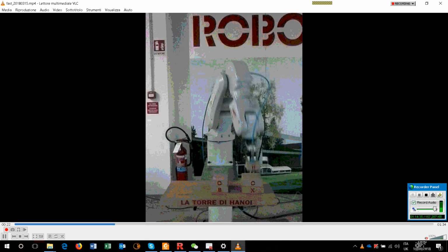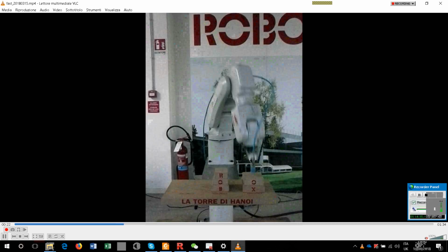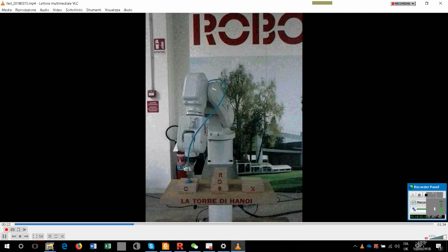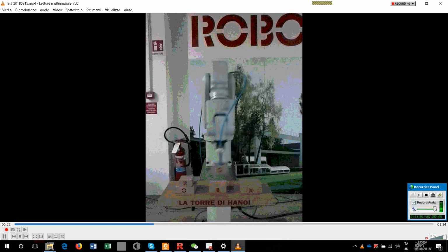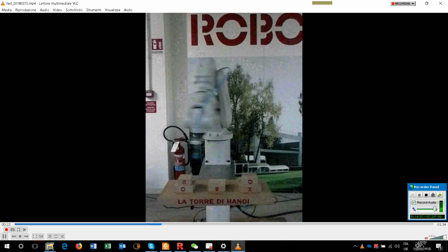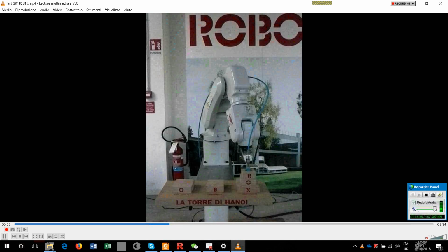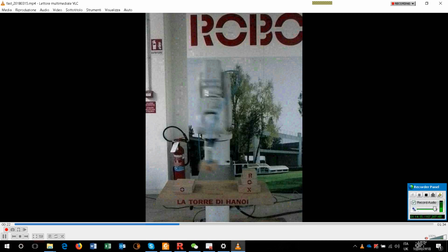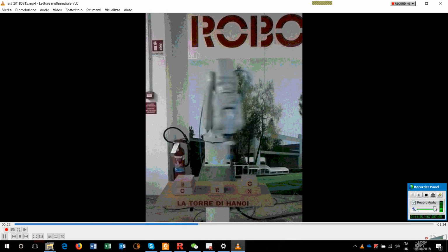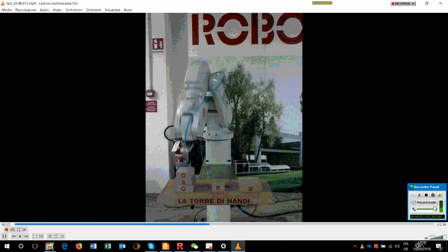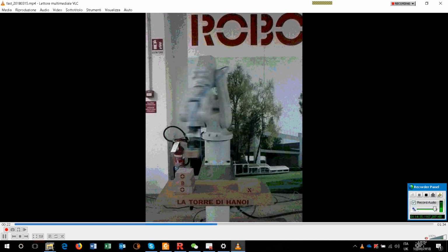This is mainly the same issue. We do a pick and place of things. You see, when we go to take a piece, we move vertical. Because after we can make some kind of very nice joint, you see. When it is moving up, it's moving blended, not corners, otherwise it would be very slow.